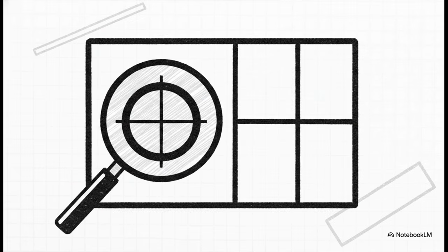Step 1. First up on the far left, we have the geometric characteristic symbol. This dictates exactly what type of control we're applying to the feature. It could be a control for form, like flatness or straightness, or maybe profile. But in our running example here with that crosshair symbol, that's a location control for position. It tells us precisely what we're controlling right out of the gate.